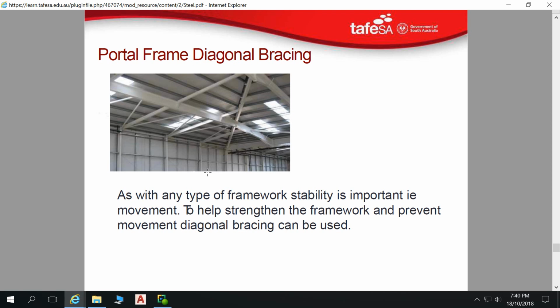Or, say you're erecting a timber frame for a house, you do your temporary strutting and temporary bracing as well. That can happen diagonally. So the way that's done is you produce a frame on the ground, you nail gun it all together, push, push, push, and you've got your frame laying there on the slab. You tilt that up. Now you're not going to have your apprentice standing there until you do the rest of your frames.